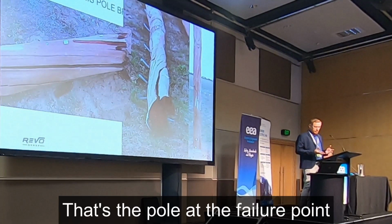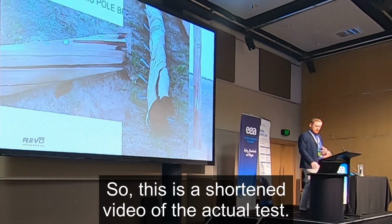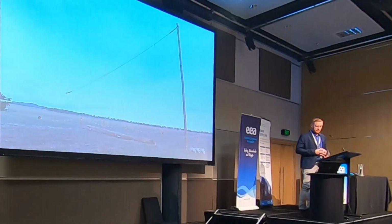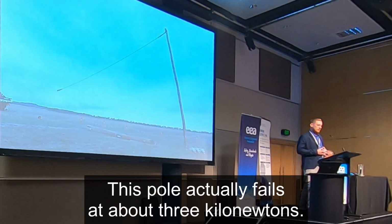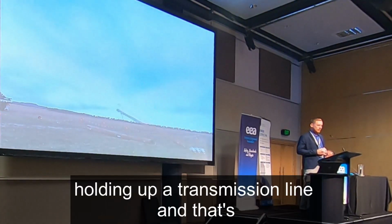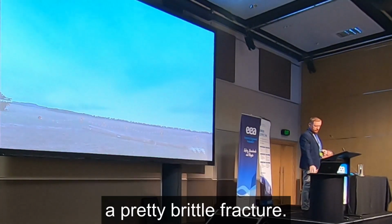That's the pole at the failure point after failure. So this is a shortened video of the actual test. This pole actually fails at about 3 kilonewtons. Okay? That's a 15.5 metre pole holding up a transmission line, and that's a pretty brittle fracture.